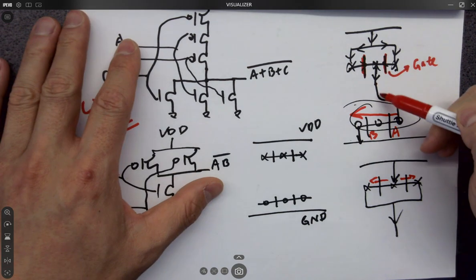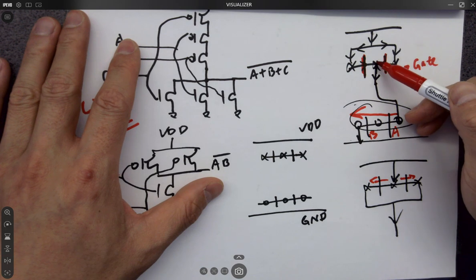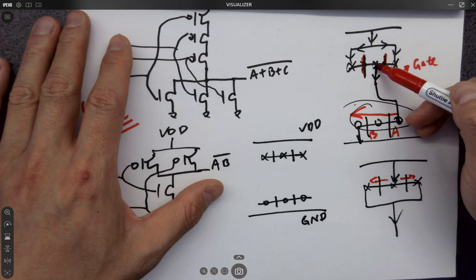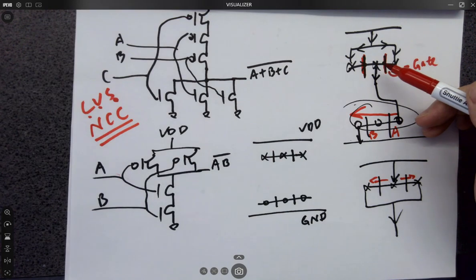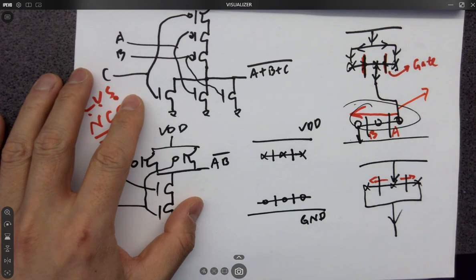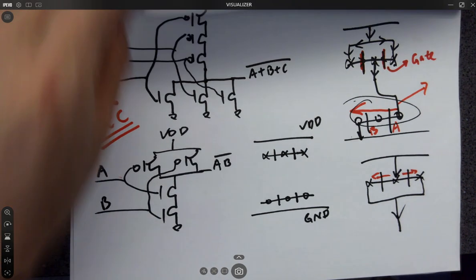What is this wire from the middle? The node in the middle represents the P plus and the via and metal 1. That's the little node part from the library. It has the diffusion, which is P plus, and the via and the metal 1 on the top. So you can directly introduce the metal 1 from that node. So that means this is going to be what? What is this wire? What are the wires shorting all the nodes together?